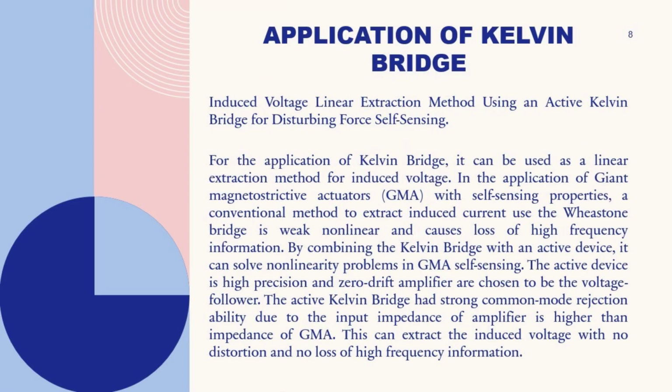Thank you. Hi everyone, my name is Jian Hui and now I will explain about the application of the Kelvin bridge. The Kelvin bridge can be used in the linear extraction of induced voltage in giant magnetostrictive actuators, GMAs, with self-sensing capabilities. When it comes to self-sensing in GMAs, the traditional method using the Wheatstone bridge falls short. It introduces non-linearity and sacrifices high-frequency information, which hinders the precision we seek.